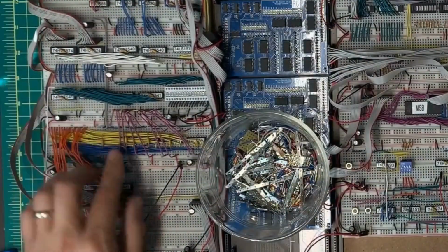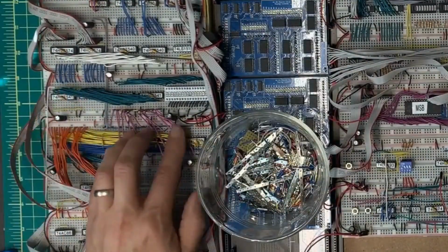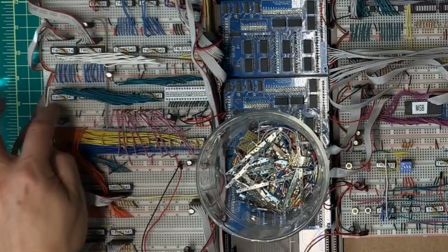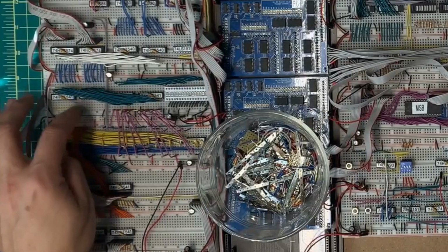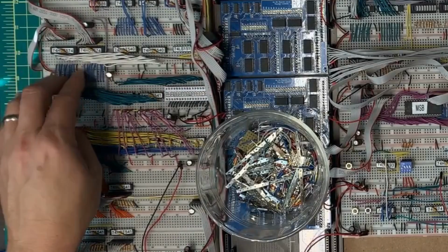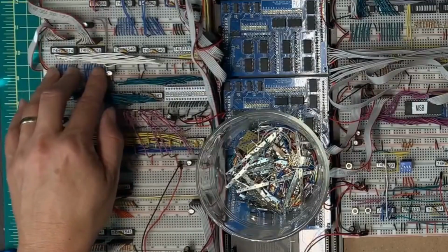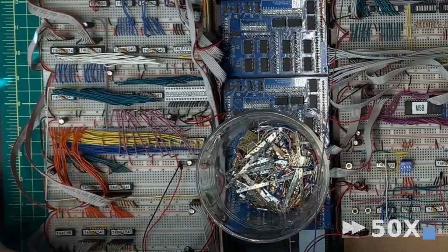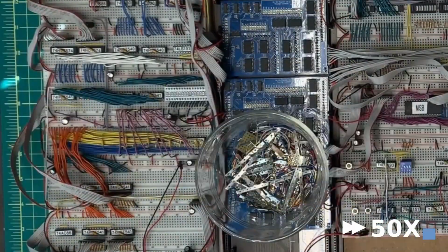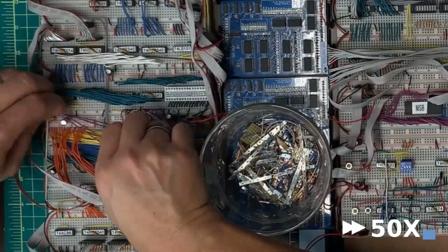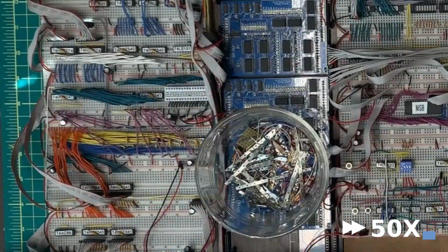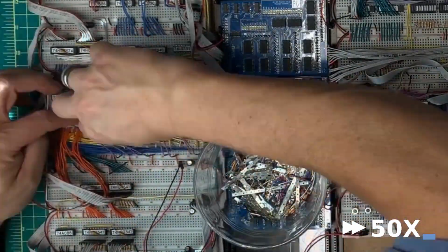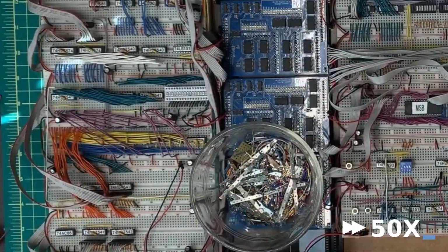Now that feels better. Like I said, the next step is to take the outputs off the ALU adder and redirect those over into the inputs of these line drivers over here so they can then be asserted out onto the ALU bus, which is represented by these blue lines up here. These are all going to have to be recut and reset. This was the fussiest bit of this entire process, as I had to keep track of the sequence of each signal and which actual breadboard connection it came out of so I could put it back in the right spot.